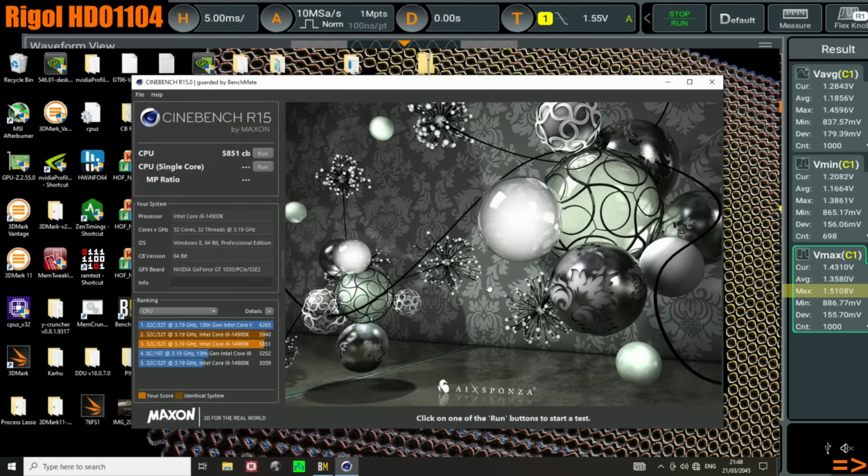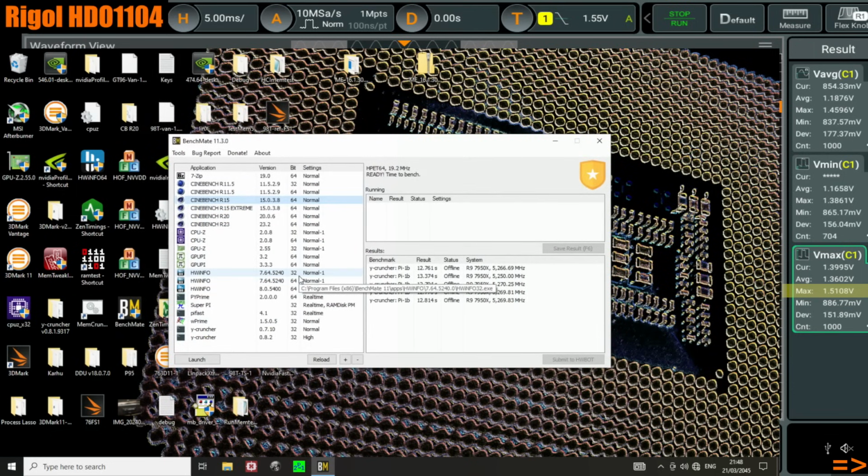And I suspect most of the reason for why that's happening is that because I set the load line so aggressive, we're probably getting quite a bit of overshoot right now. But that is better than having the CPU request insane VIDs, because short spikes due to overshoot are better than long spikes due to V-droop compensation. Or at least that's my thought process on that.